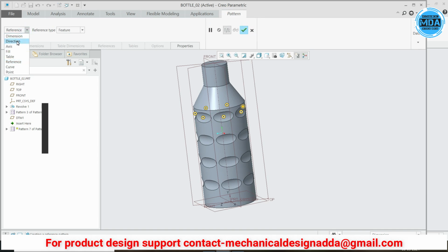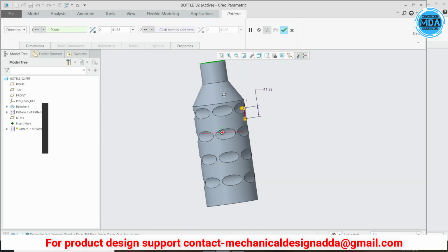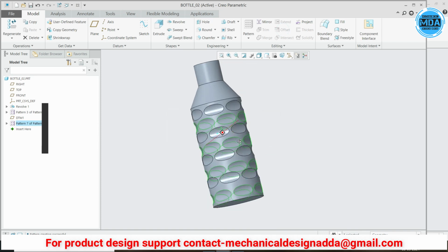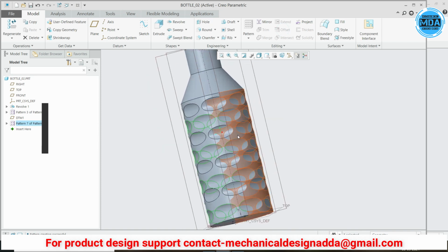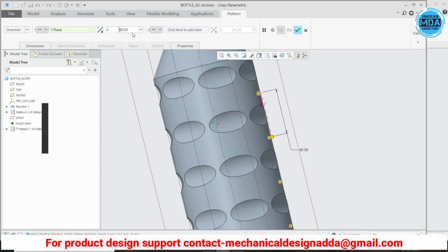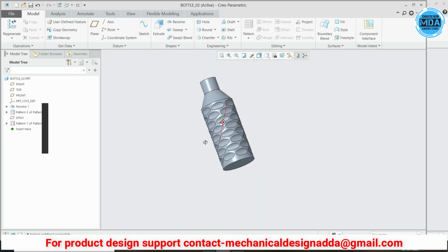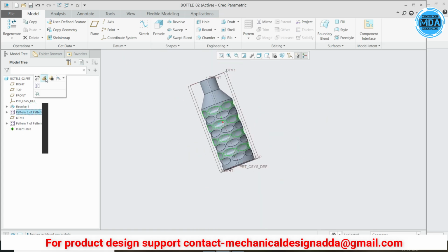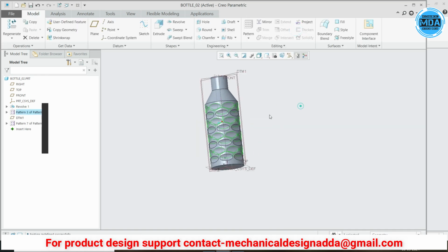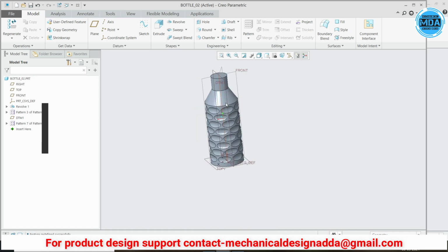So in the directional pattern, this side, and flip this direction, and say 95, and it will be 4 same. Okay, so you can see here the 95, it is keeping distance, so keep the 90. No, it is in the middle, because in the previous pattern we have maintained 90, so we keep the same pitch. Okay, so our basic geometry is completed.